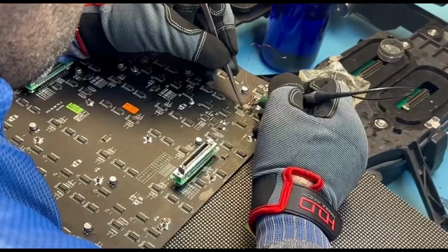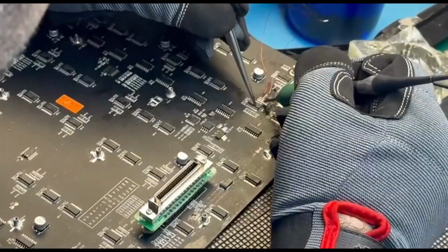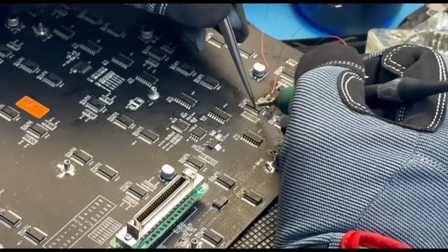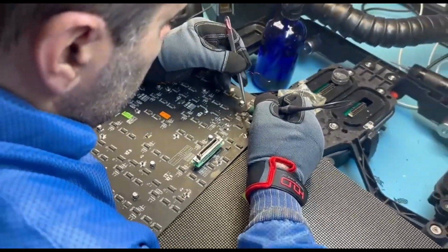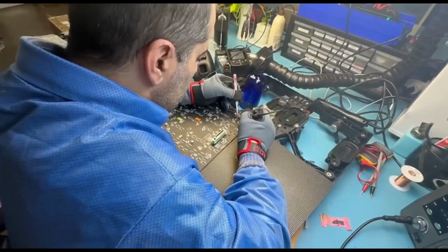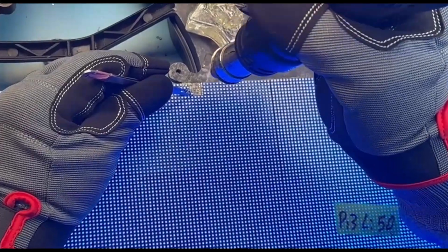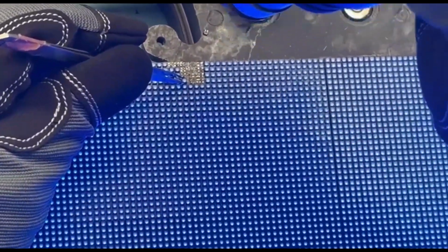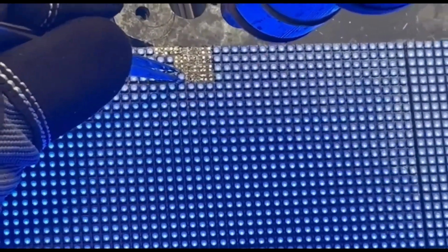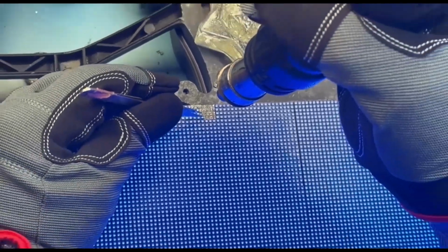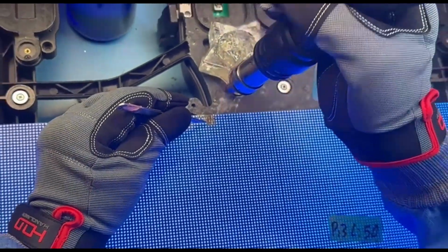Repair and maintenance. Focusing a bit more on maintaining and repairing the X2V module would help in better product selection. The X2V is more difficult to repair than normal because of a few reasons. First, it is harder to fix the LEDs because there is not much space to work with, and there is a chance you might accidentally take off pads from the PCB while fixing it.